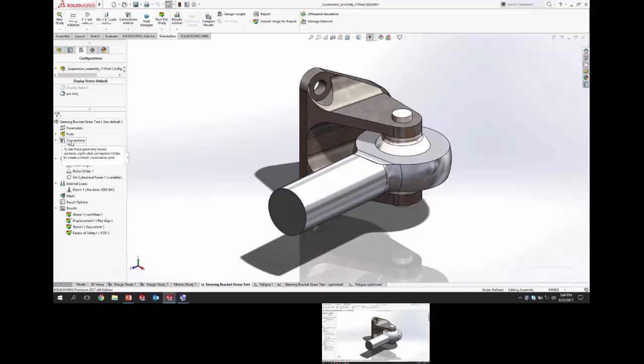In assemblies, connections are even more critical because connections include not only things like replacing bolts for a bolt connector, which gives you the behavior of the bolt, even preload or pre-tension on bolts, pre-stress.